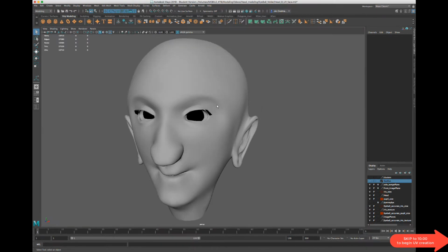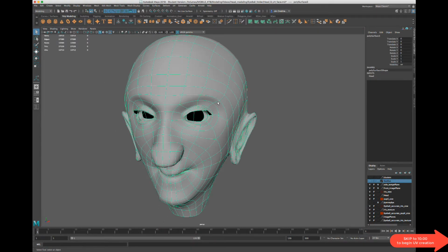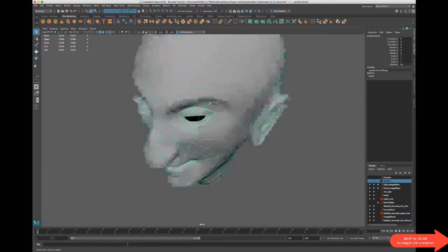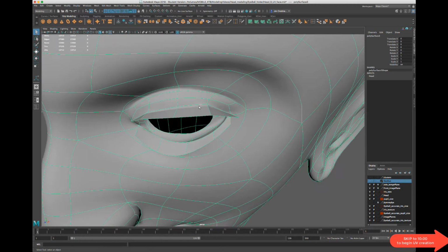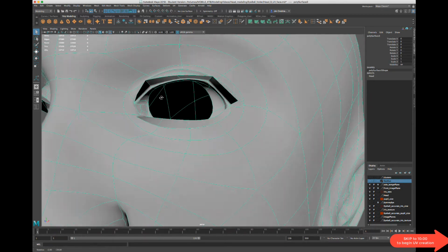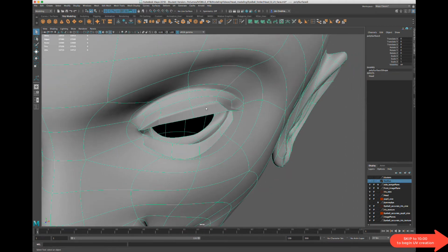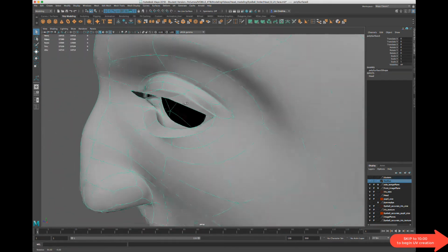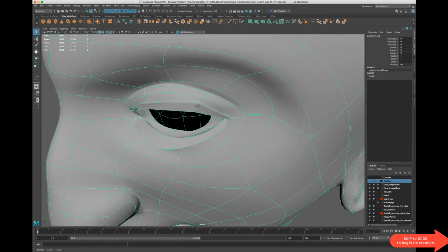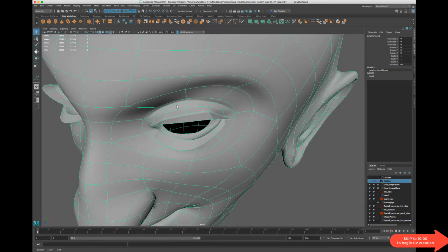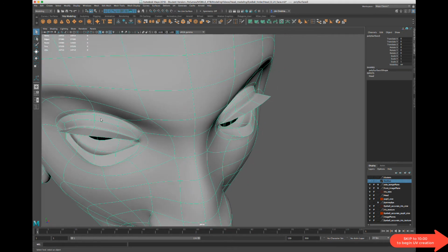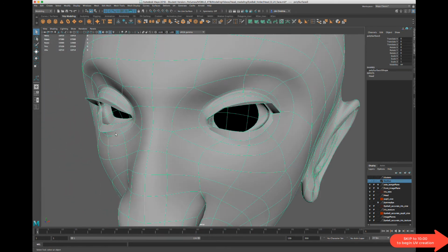Now, before we set a projection and we start with our initial UV work on this head, there's one thing we have to take care of, and that's the eyelashes. We extruded the edges to create these eyelashes, to create nice, thin, and simple geometry. But it can create, as we saw before, a possible non-manifold topology error if we didn't make that fix. If we already did, it's fine. But also it creates a problem with the UVing and unfolding process. If you made eyelashes on your character similar to mine here, you may have a problem with non-manifolds.